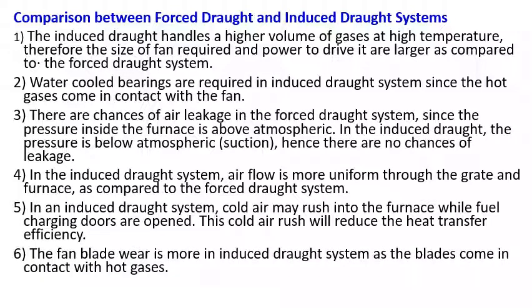Right, the fan blade wear is more in the ID fan system, because I am handling the dirt, but in the FD fan the ambient air does not have dirt compared to the flue gas. Therefore, the life of the FD fans is much higher.